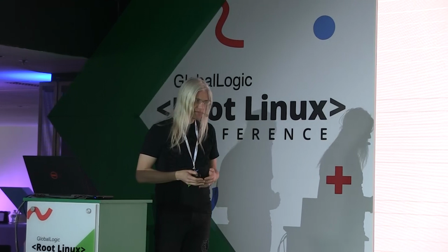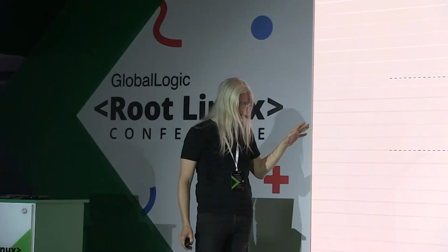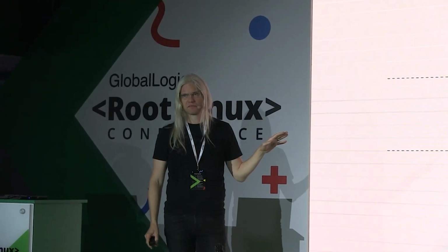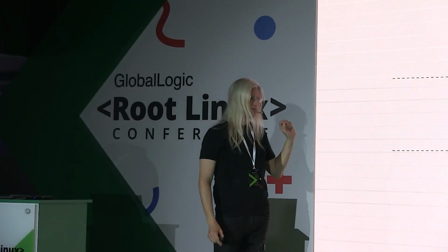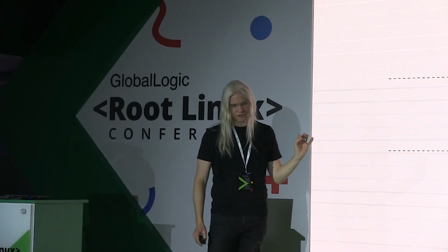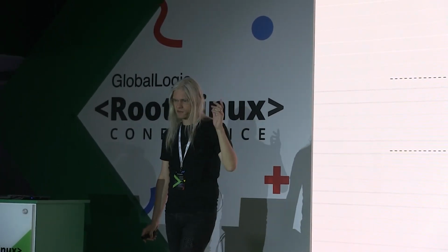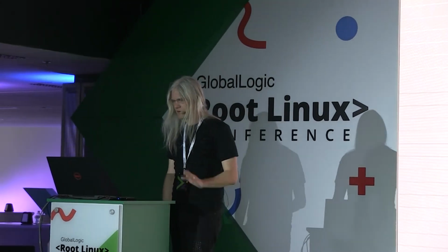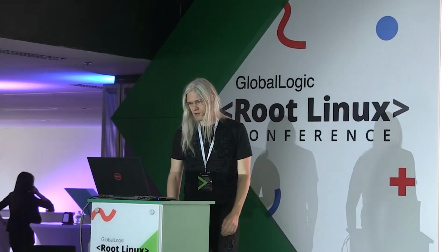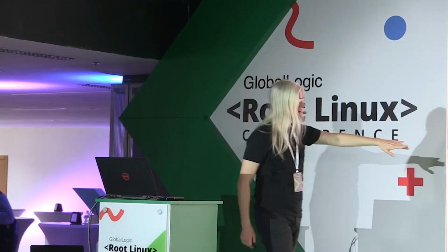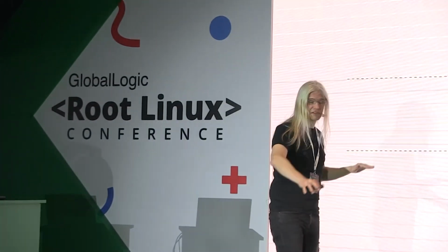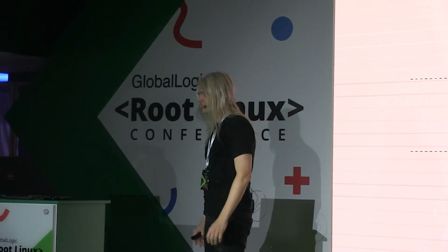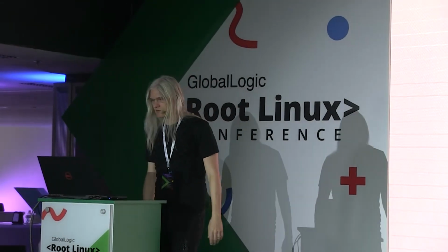It is usually routed out through a specific physical pin on a package. Not always. There are exceptions to that. So the GPIO is just some output of some hardware where you can control it low or high in a generic manner. It's not there for a specific purpose. It's there for any purpose. And they can be in output, like here, I drive it, I say go high, go low, and so on with software, and it can be input. So I read it and see, is it high, is it low, what is it?